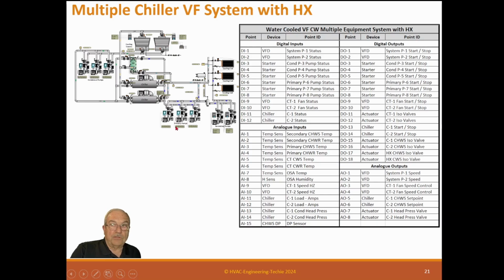But if for some reason you have to switch back, we have a head pressure valve on here, and this chiller will automatically control that head pressure, keep its head pressure up so it doesn't go real low at low temperature. Because all chillers require slightly different pressure, whatever that manufacturer needs is what he'll get. But that's a safety in there, switching back from heat exchanger. And we'll go through that in the sequence.